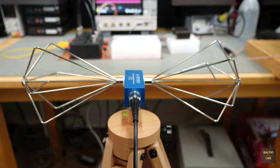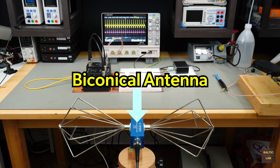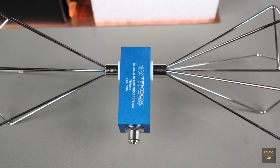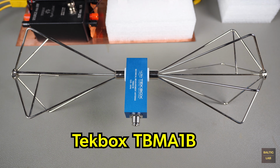Due to the chaotic and complex nature of near field behavior, a non-standard far field measurement of the electric field strength is also performed. For this purpose, a calibrated biconical antenna, the TechBox TBMA-1B, is used.